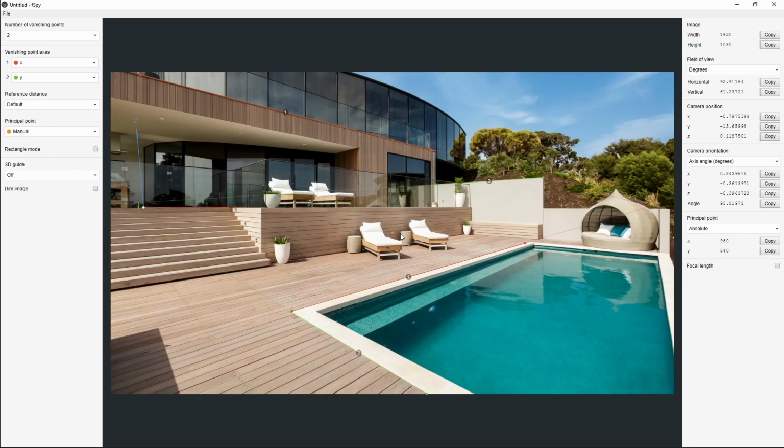The rule of thumb is grab the principal point, this little orange dot, and drag it along the direction of the parallel lines, those without the vanishing point. So if the parallel lines in our image are vertical, we must drag the principal point vertically, up or down. This will rotate our z-axis and will let us align it with the image.